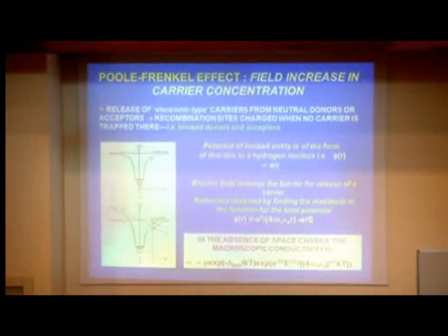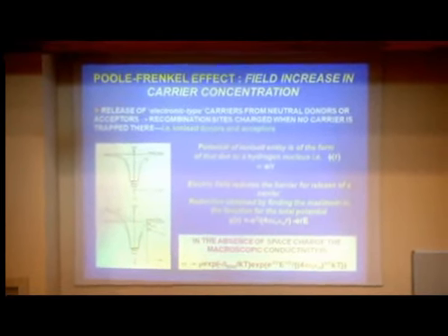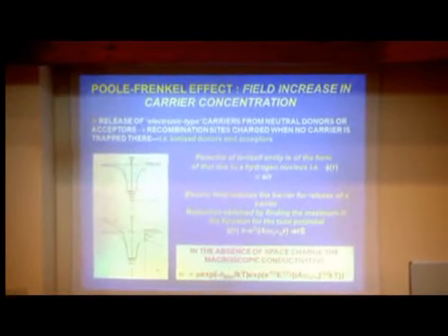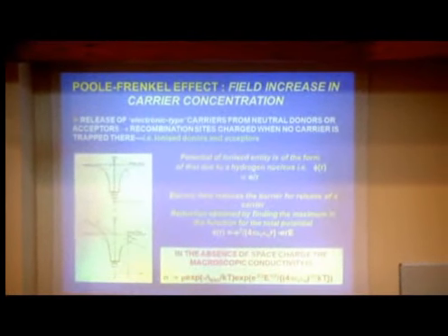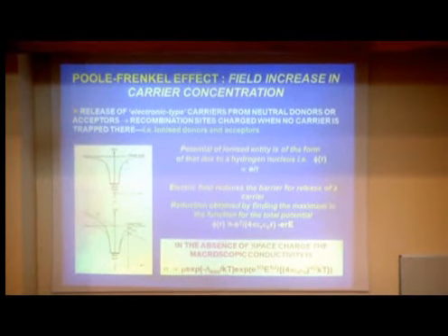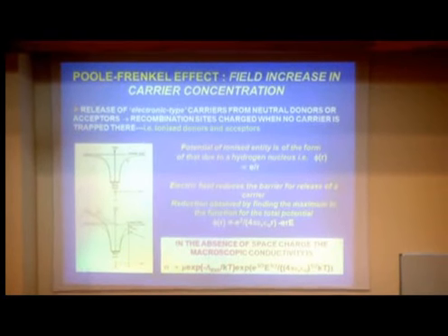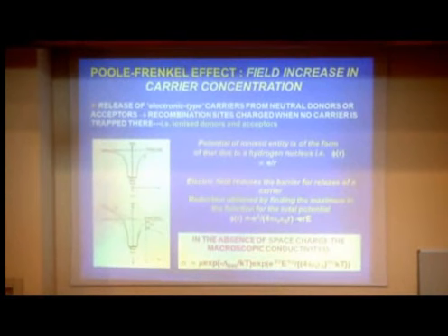Now, what about the number of carriers? Nobody's done any work yet, or very little work, on the field dependence of contact charge injection. I think I had a paper at Winchester on that, but I don't want to labour that. Nobody's done any work on the field dependence of injection from interface states.